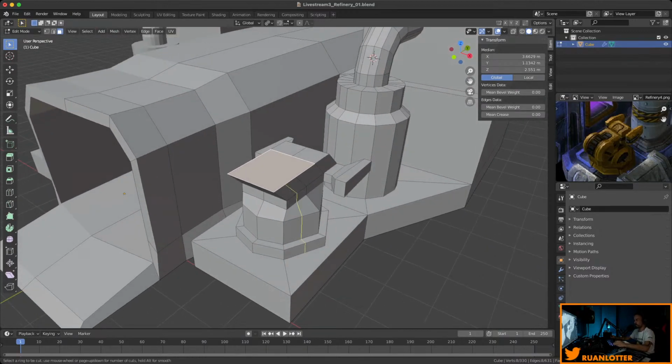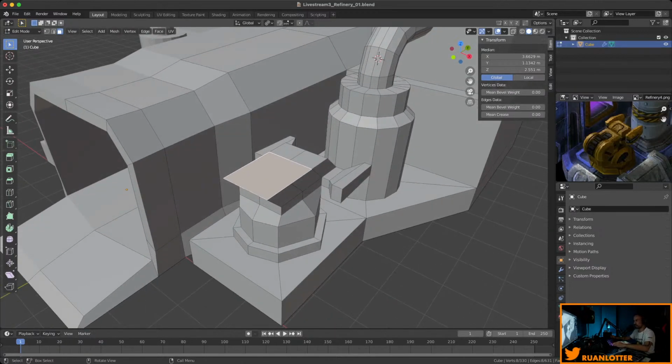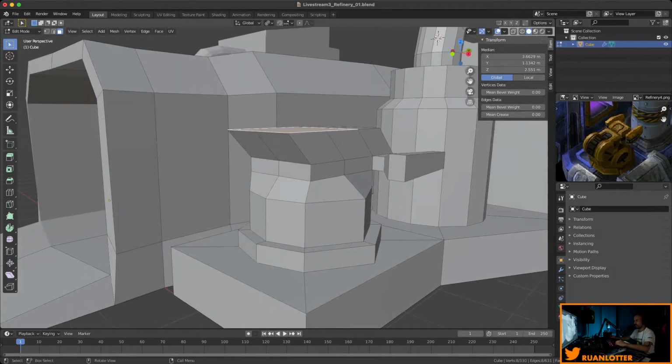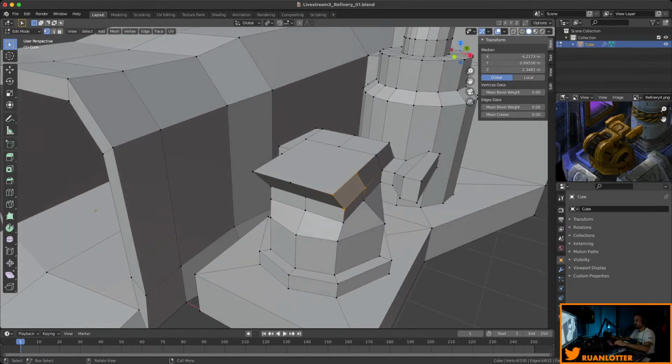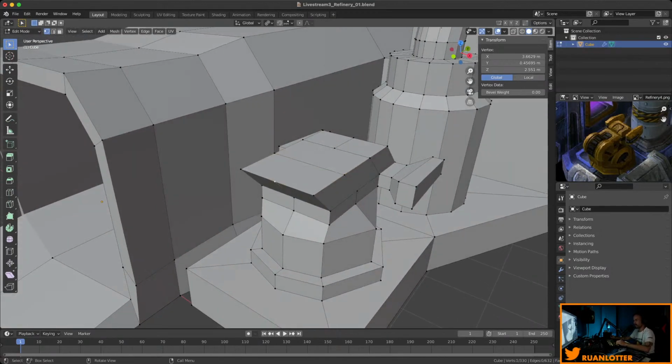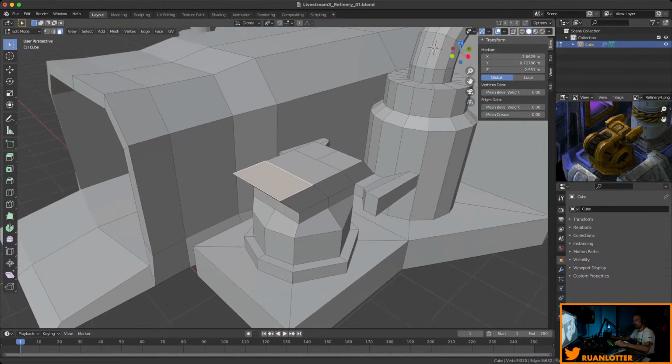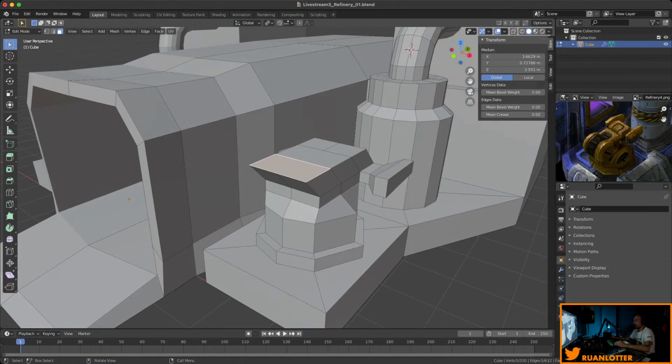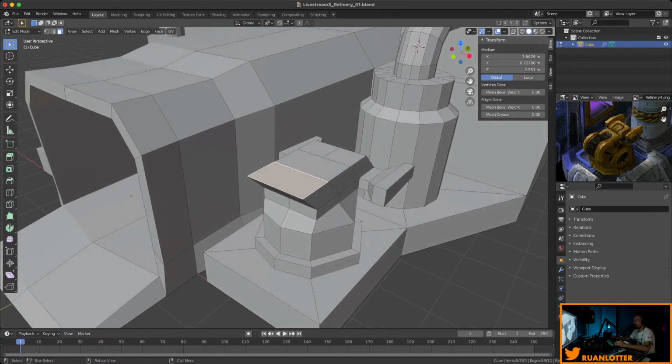Let's do a loop cut. Ooh. Or not. Let's do a subdivide. Also not. What is going on here? Do we have vertices? Yeah. So I'm going to connect those two using J. And then the same with these two. Well, I don't really have to. I can just use this one thing here. So we need something that looks a little bit round here. I don't know if I'm going to create a cylinder maybe and add that in as well.